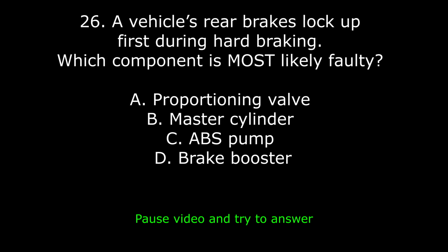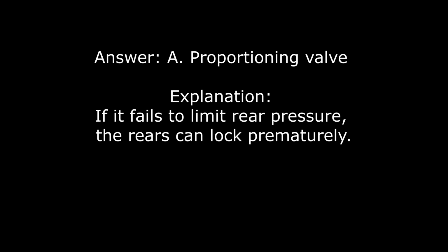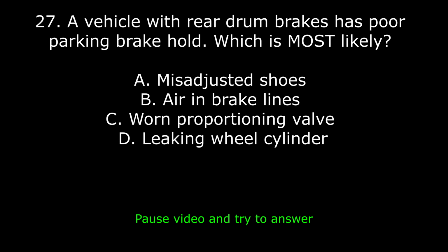26. A vehicle's rear brakes lock up first during hard braking. Which component is most likely faulty? A. Proportioning valve. B. Master cylinder. C. ABS pump. D. Brake booster. Answer. A. Proportioning valve. Explanation. If it fails to limit rear pressure, the rears can lock prematurely.